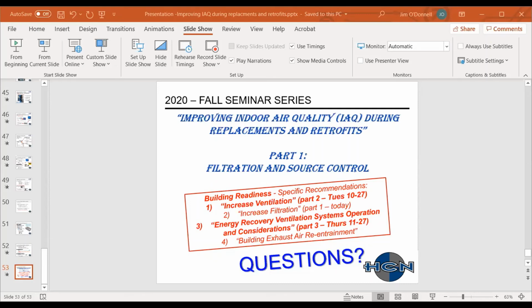That's just the salient point they needed tested by the people that were testing it. They were concerned at 250 feet per minute. At 500 feet per minute, where we have done it in spaces, we find that as you increase the velocity, you get better distribution within the space, and you get more effectiveness that way.